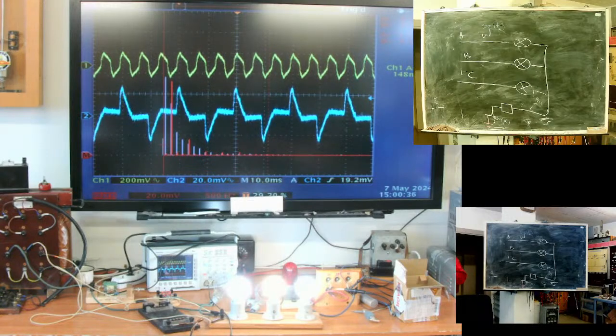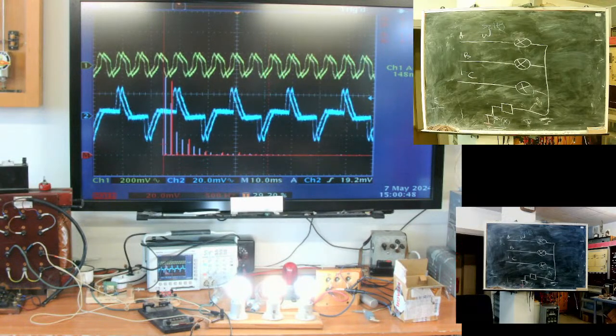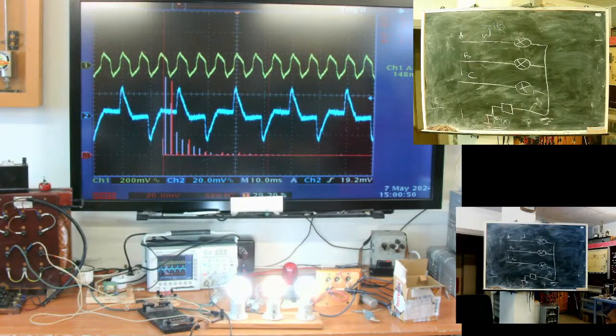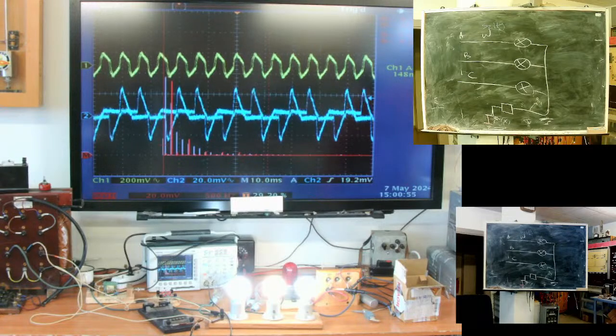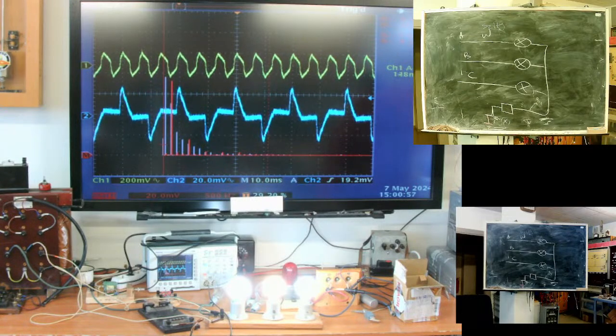These peaks are determined at the moments when phase voltage is over the capacitor voltage. So the angle between peaks will be approximately 120 degrees. The phase angle at the first harmonic determines the moment when the peaks arrive.